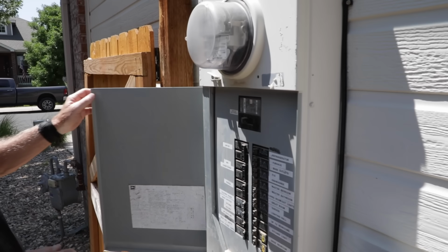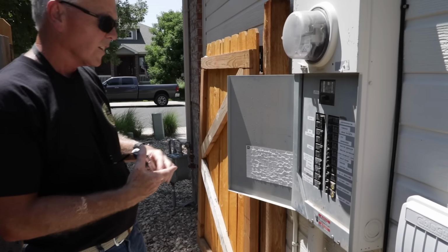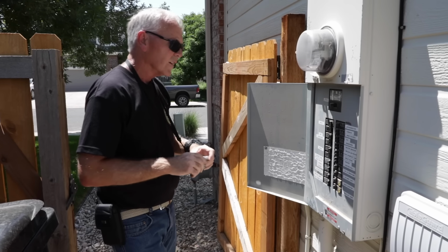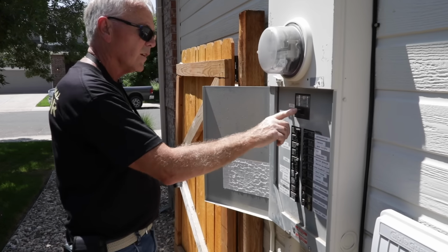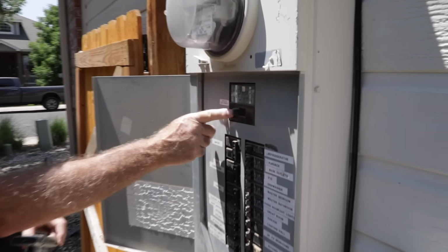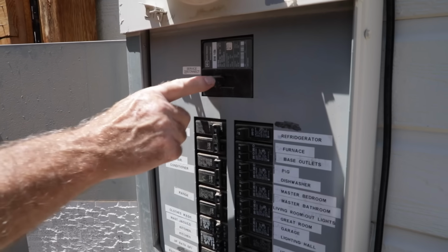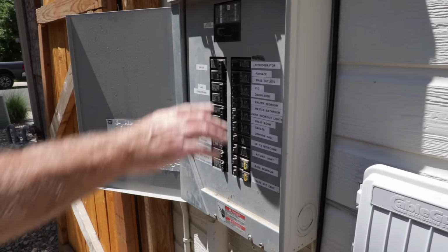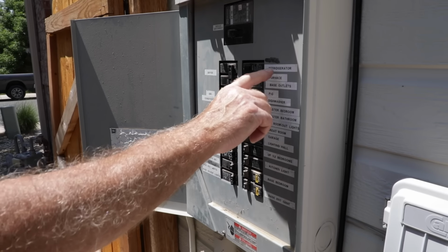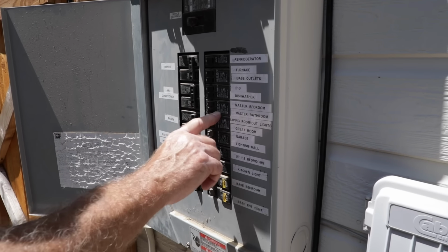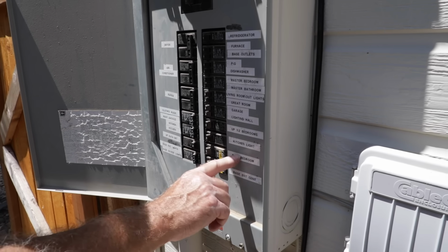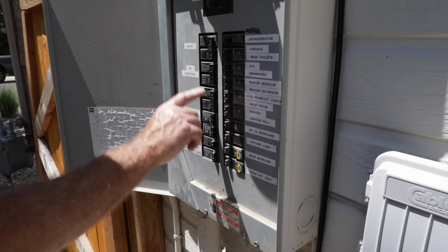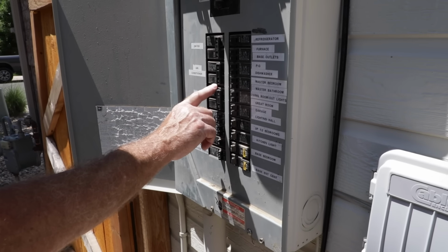So now we're going to open up the circuit breaker panel here on the bottom. This is an exterior panel. I'm going to take a photo. This is a 200 amp main disconnect. There's a 200 amp breaker. By shutting this off, that would shut everything down below on this panel. So now I'm just going to take a brief view here of what I've got for circuit rating on these circuit breakers and look at where they're feeding, what rooms. Make sure that we don't have any breakers that are too big or oversized or undersized.